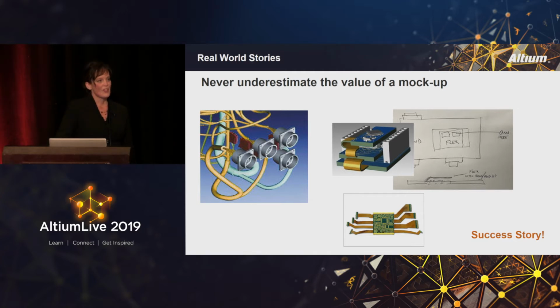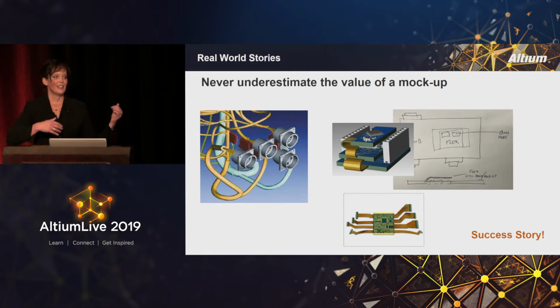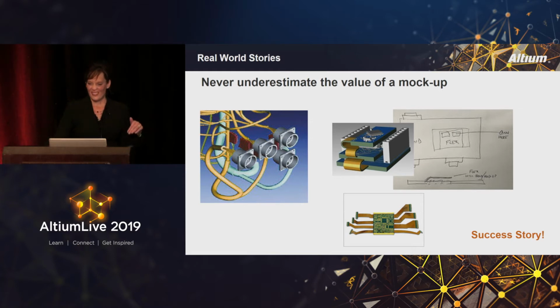And when I was talking to people about this presentation, asking for stories and some of their best advice, a couple of things came along this same line, especially when you're working with flex. If you're going to work with a number of flex, start the design with the flex, because it's really easy to get things mixed up when things are bending and folding and going around corners, and the pinouts can get mixed up pretty easily. So they recommended starting with the flex.